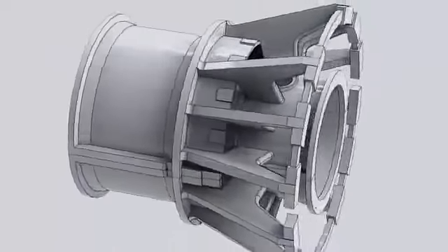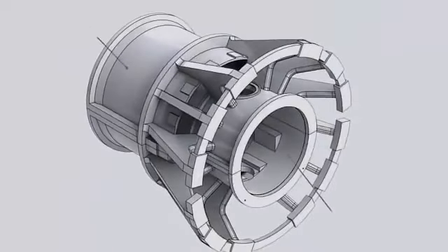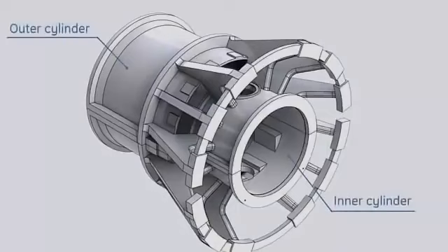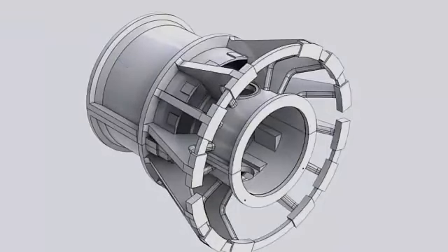The discharge casing consists of outer and inner cylinders. These inner and outer cylinders are connected by means of 12 struts. These struts flare out to meet the large diameter of the turbine shell, while providing spacing for transition pieces in between.